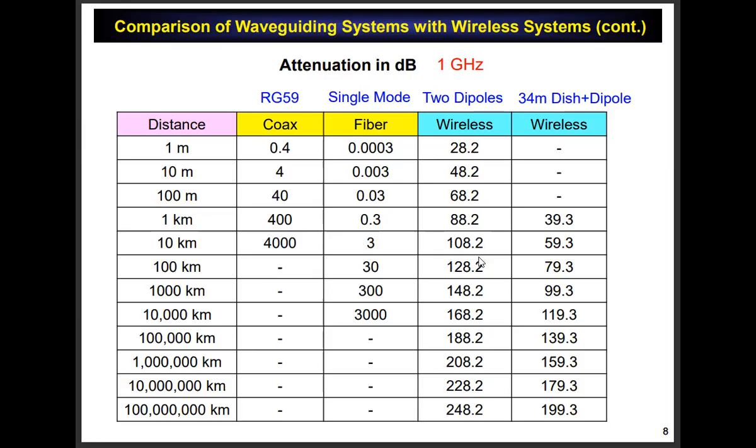And that's what they're doing on these repeaters too. You see on the towers, except it's a wireless system. So a lot of times you'll have a tower and you have two horns, one pointing this way, one pointing this way. So this one is receiving the signal from way over there, 100 miles away, and then the system is amplifying it, possibly digitally reforming the signal too, and then retransmitting it out of this horn, right? So it's a microwave repeater on the tower.